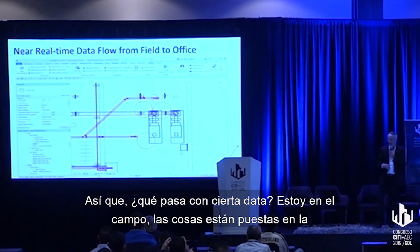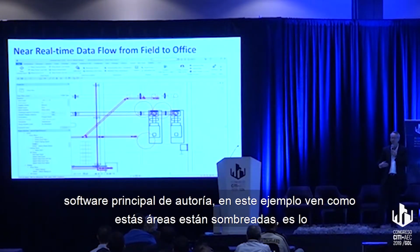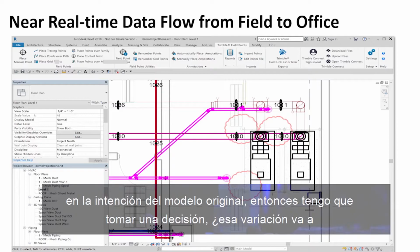So what happens with some of this data? I'm out in the field, these things are being laid out in the exact location, they're starting to become constructed. What I can do is feed that back into my authoring CAD software. So in this example, you see, if I use a laser pointer, these areas that are clouded out are the point data coming back to the original BIM model, and the marked out area here is showing where there's a deviation from the original design intent.